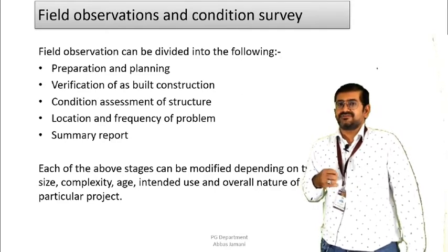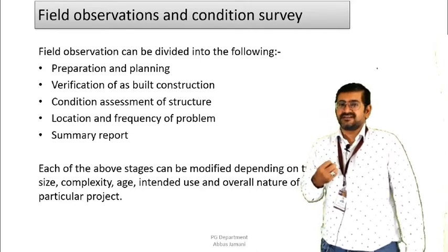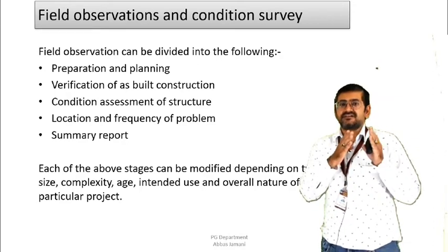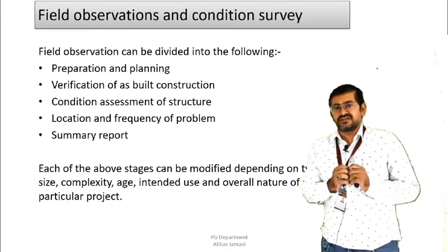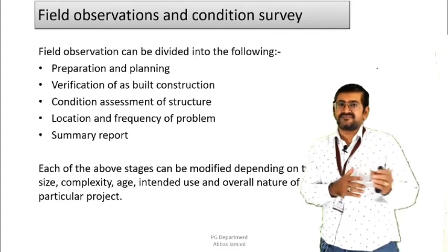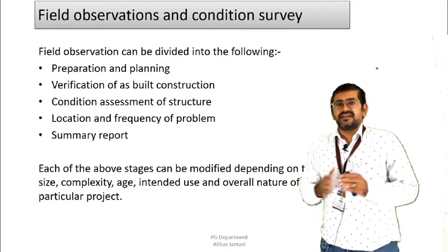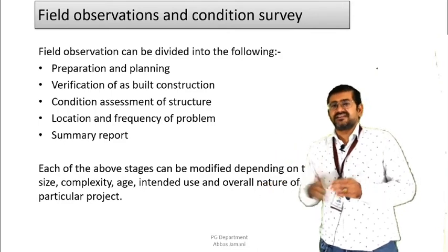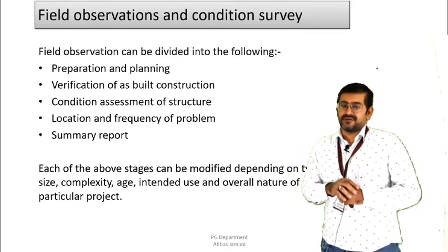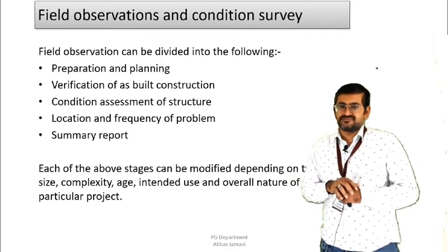So you need to prepare certain documents in your office also before going to visit the site. For example, you need to plan in such a way that the structural aspects of the site visit will be listed down in this particular document in this fashion. If any alterations are there, then it will be mentioned in this sheet. If the dimensions need to be cross-checked, then these dimensions will be checked: height of the floor, span of the member. Then if deflections are there, what is the actual deflection observed on site?